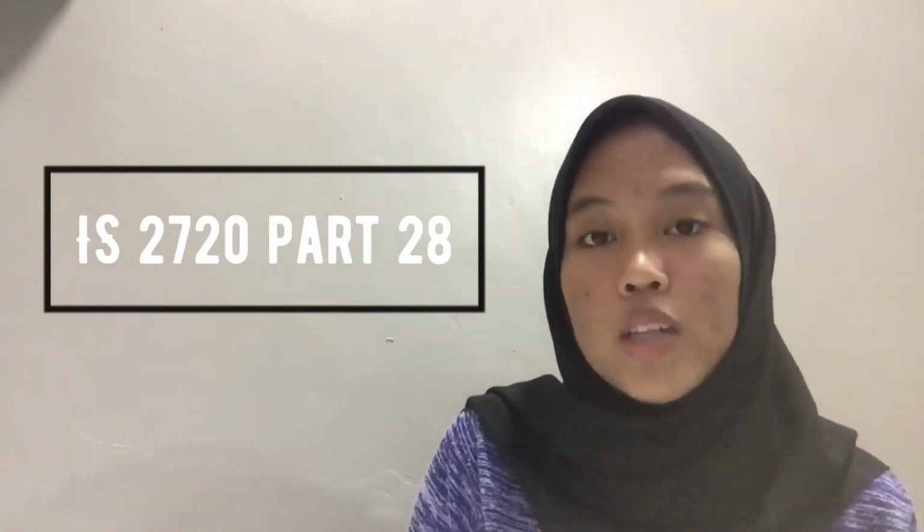I'm going to share a little bit about the background study of the field density test using the sand replacement method. A soil compaction test uses one of several methods to measure dry density and moisture content of soil in place. One of the used methods is the sand replacement method. The sand replacement method is used to measure in situ density of natural or compacted soils by using a sand pouring cylinder. The procedure, materials, equipment, and specification of this test are based on Indian Standard IS 2720 Part 28.